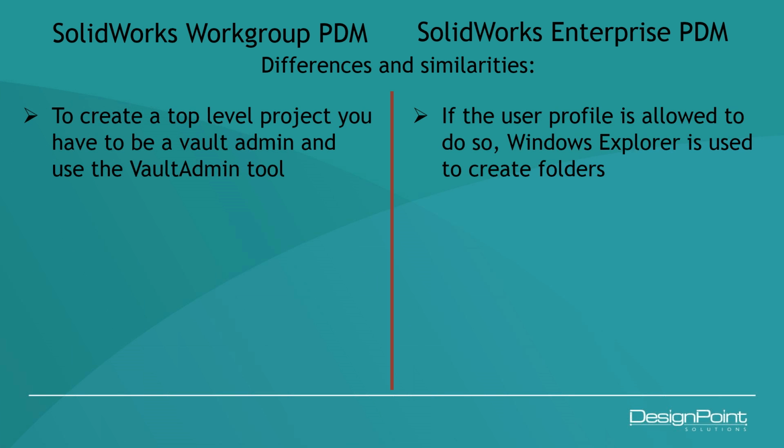If you want to create a top-level project in Workgroup PDM, you will need to have access to the administration, and you need to have the password for the admin user. A regular user is not allowed to create a top-level folder. In Enterprise PDM, if the user has the permissions to do that, they can definitely do that.